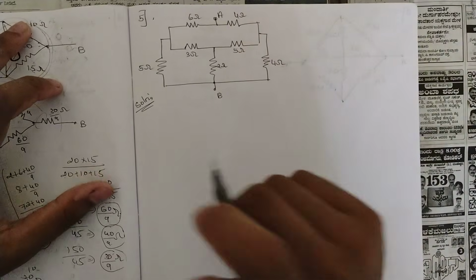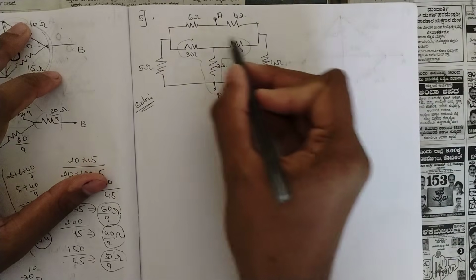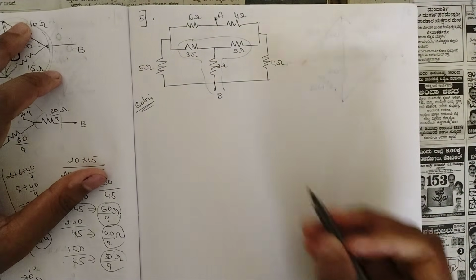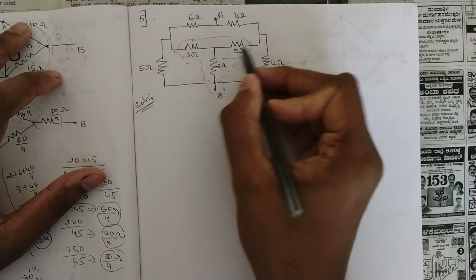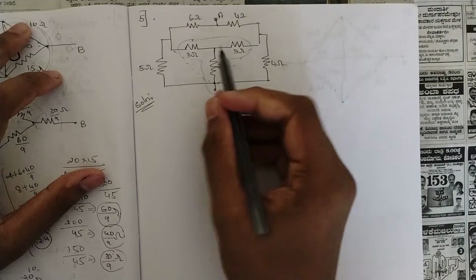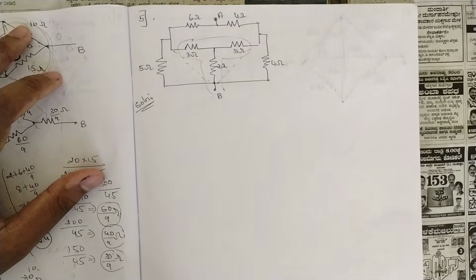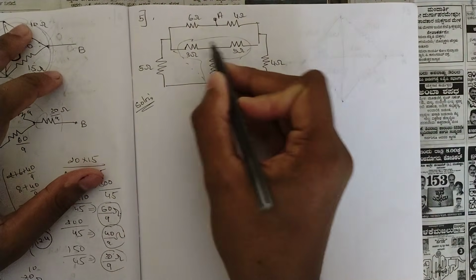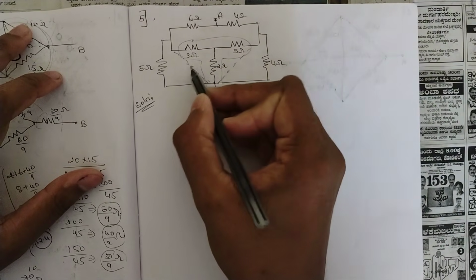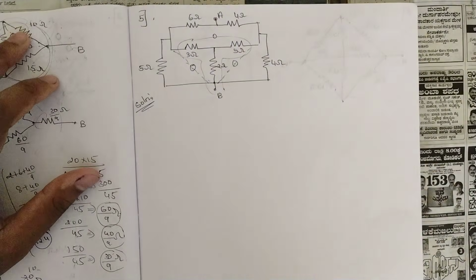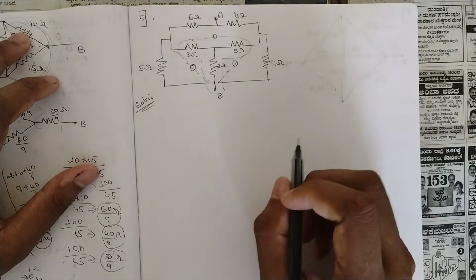So this is here the first circuit. Analyze it. You can see that here we have one star connection, right? So now for that we should be finding the equivalent delta connection, that is this triangle. So this is one star connection, or we can call it a T connection. I told you a star network can also be called a T network. Okay. So for this now we should be finding the equivalent delta. Okay, see, I have drawn the dotted lines. We should be finding these three values here, the three resistances, and you should be replacing this by the delta connection.